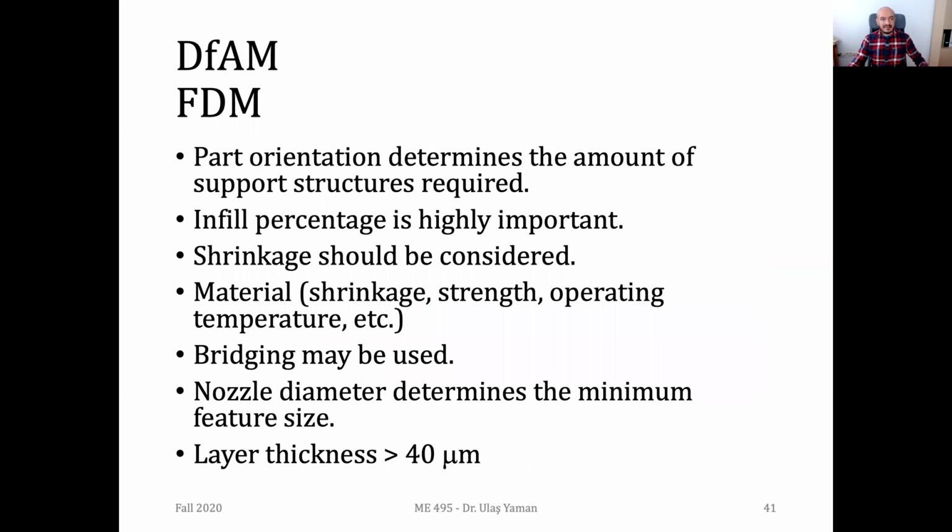Now let's discuss these processes one by one. The first one is FDM or triple F. If you remember, in this process, we need to use support structures for overhanging regions. And that's why the orientation is quite important. While designing, you need to be aware of this problem. Do you remember the dancing snowman? They had a special part inside of the snowman so that without any support structure, they had a functional